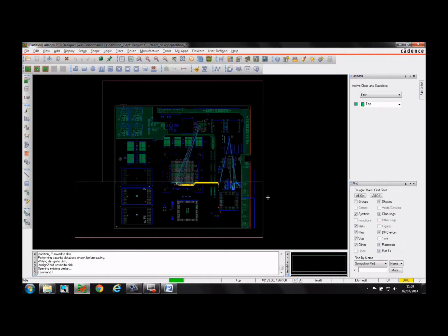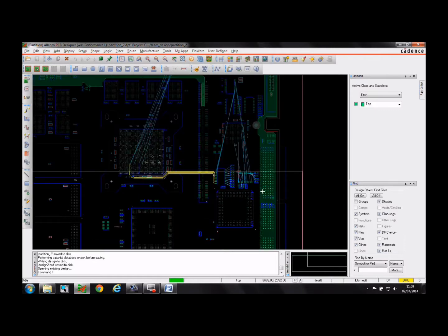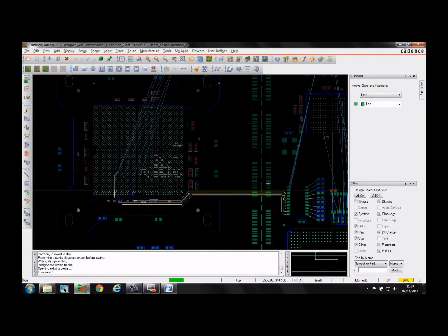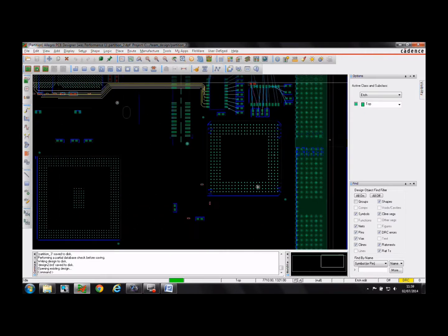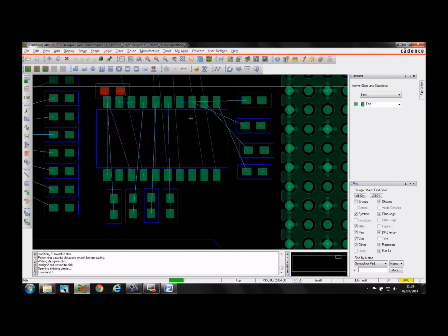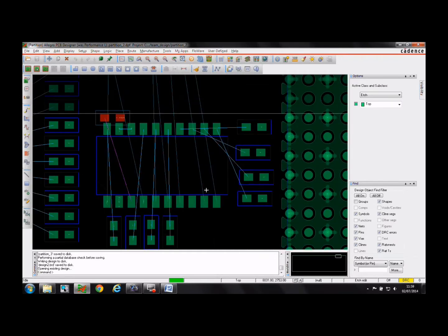Traditionally, from a working point of view, you'll see the stuff that I haven't got access to, that's not in my partition, is a bit dimmer than the rest, and there are settings for that if you want to look at that. This is the partition where I'm allowed to work, and in this scenario, maybe I want to move these 8 resistors to the outside.